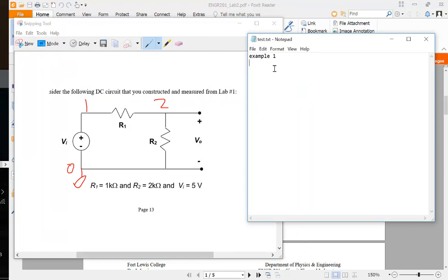Start with the voltage, like V1. You just have to start with V. It can be V1, can be VR, can be whatever V, right? It has to start with V so the SPICE software can recognize the voltage source. I just call it V1. And for V1, the nodes have to follow the order from anode to cathode, so it's going to be 1 to 0, right? That's a voltage drop. From 1 to 0, it drops 5 volts, for example.